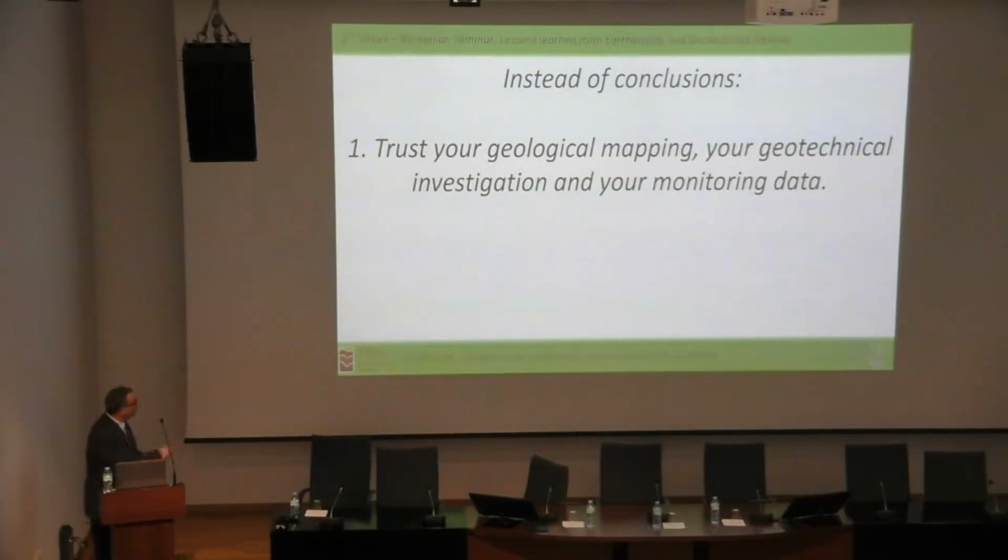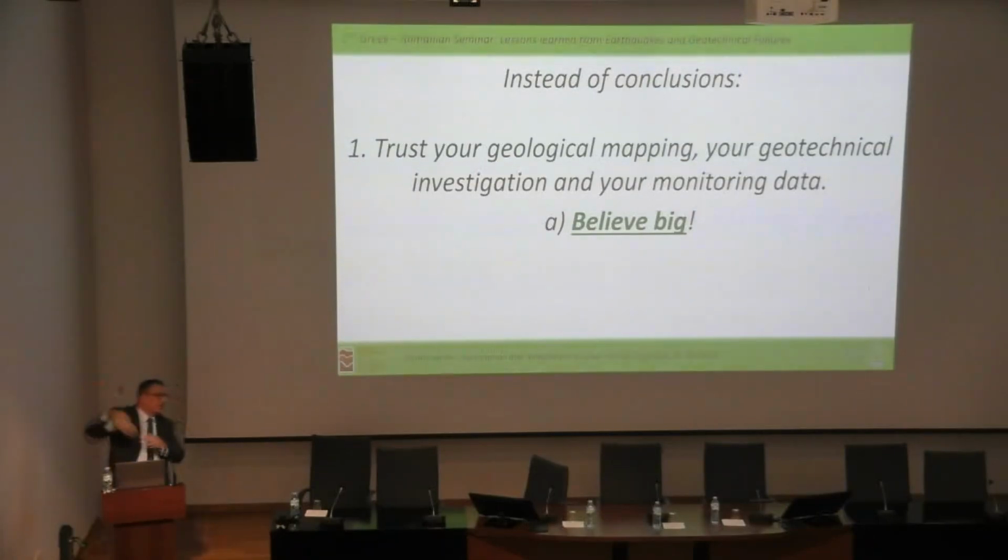Trust your geotechnical investigation, your monitoring data. Believe big. If I had €1 for every time I have heard, oh, come on, it cannot be up to there. It cannot be this deep. It cannot be this wide. Why do you ask us for an inclinometer up there? It's rock. Just €1 for every time I have heard this comment. I would be a rich man. So believe big from the beginning. If it ends up smaller, fine. It ended up smaller, but believe big from the beginning.